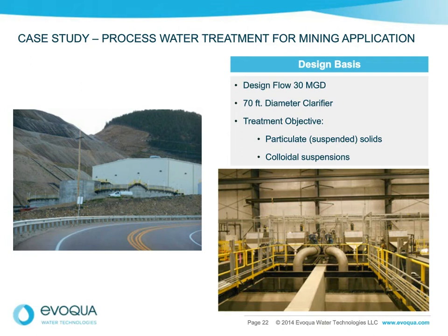As a result, inline shear mixers, magnetic recovery drums, and a 70-foot diameter circular clarifier was installed. Not only were they able to meet their objectives, but they were also able to increase the yield of their product from their operations. The client partnered with a well-known engineering firm from the Northeast to help them execute the project.